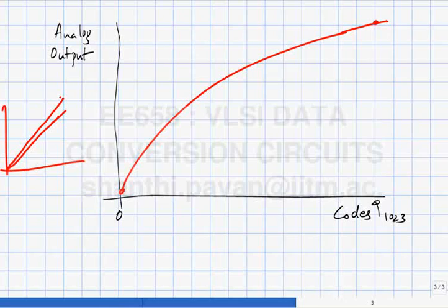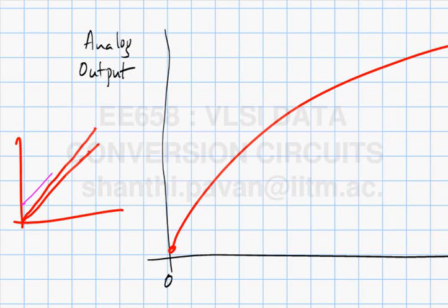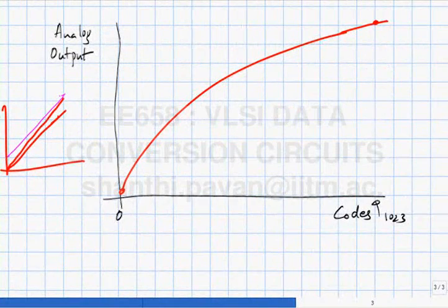So we should be able to take out the same thing with offset also. If the curve was like this, the pink one here, then there's nothing really wrong with the converter, it's just that all this characteristic is completely shifted. So with the offset curve, if I simply directly use the definition of INL with the wrong LSB size, when I compute DNL of this curve, what would I get? On the pink curve, what would I get if I compute the DNL? I would get 0, alright, but what would I get as INL? I will get a constant corresponding to this spacing, correct?